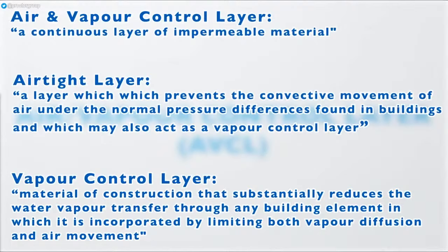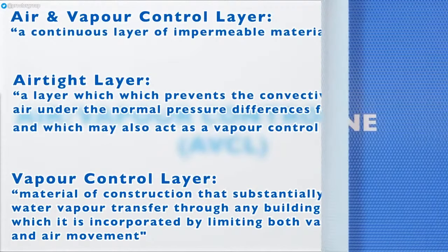To be fully effective, an air barrier has to be fully sealed and continuous. While this is an important consideration regarding vapour transfer too, there is a little more margin for error before a badly sealed VCL will create condensation problems. Poor air barrier performance, however, will impact the building energy performance calculations and is subject to pre-completion testing.